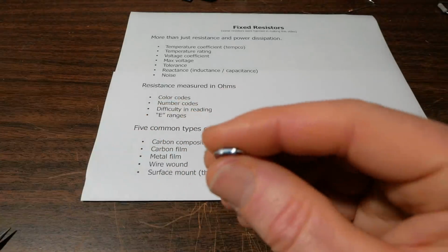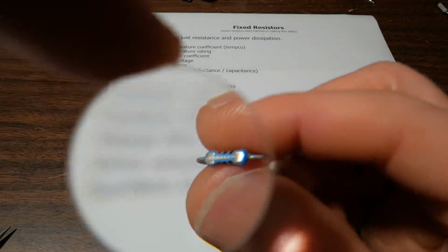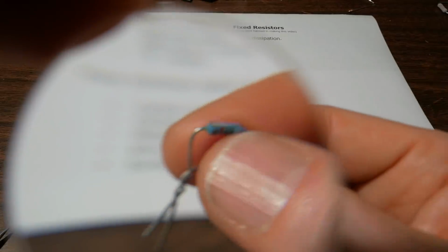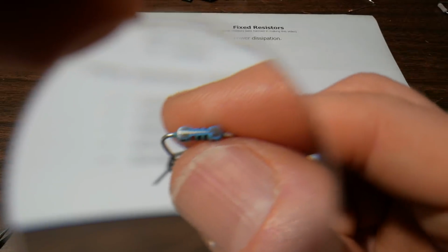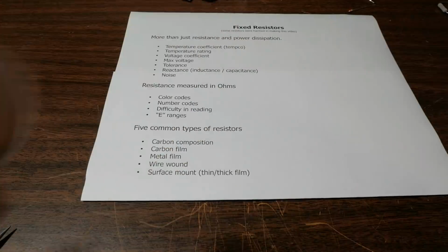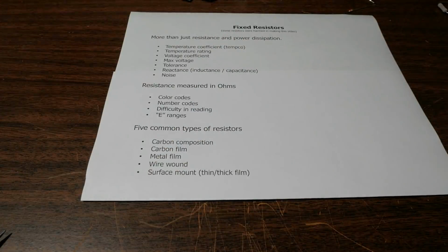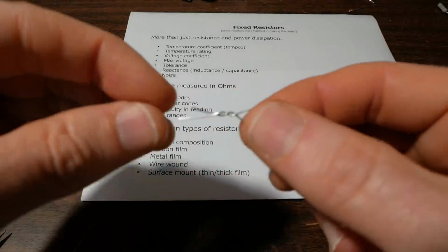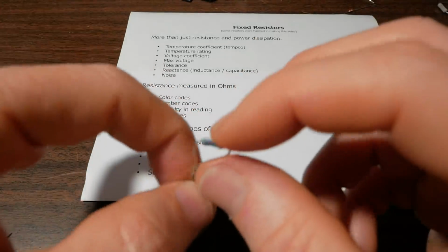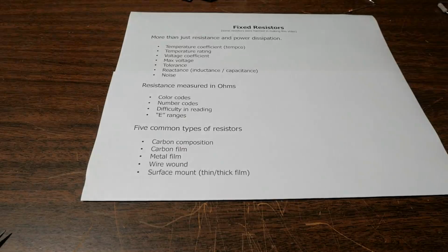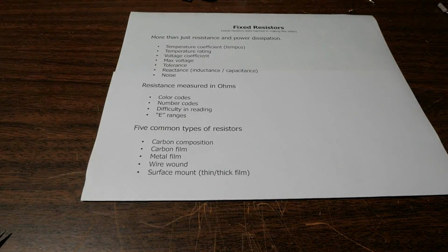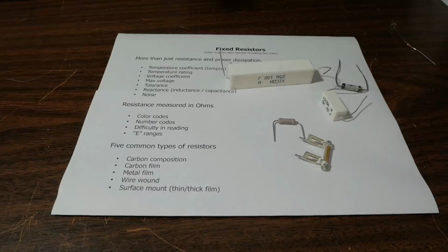I've read that it can be in the VHF range. But there's really very few turns, maybe 6 or 7 in this case. I believe this is a 20k ohm resistor. It's on a very small former. I would think that even the leads have more inductance than the small coil effect of the internal resistor design.